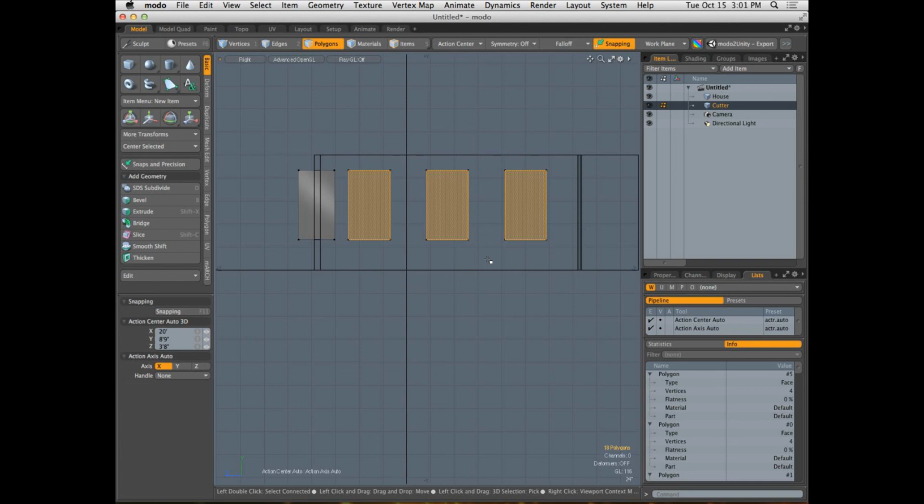Go into your polygonal selection set and select that polygon. Perfect. Let's go into your polygon set of tools. In the double arrows, click on it to get the rest of the tools. Let's do reduce, and do merge. All right, what did that get us? Another mess of stuff, with some weird little bits. You know what I would do in this particular situation, Brandon? I'd cut my losses and just remake the cube.